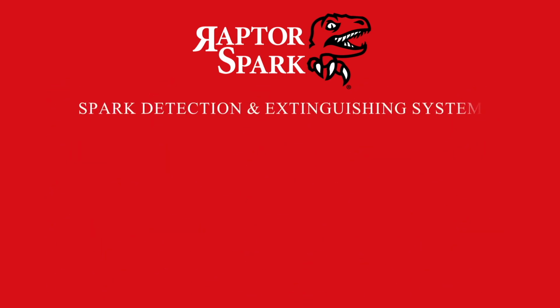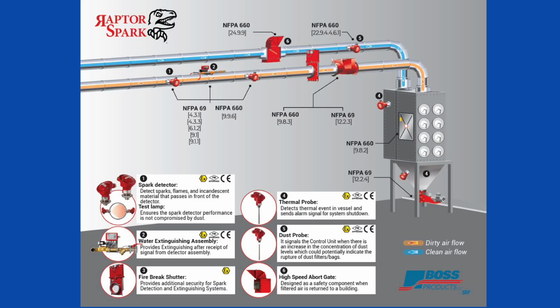Next slide, Andy. So here's sort of a flow chart and basically equipment lined up in a collector application. As you can see, at item 1, there's your spark detector. Item 2 would be your water extinguishing. And then as I talked about before, we can do a redetect and a fire break shutter.